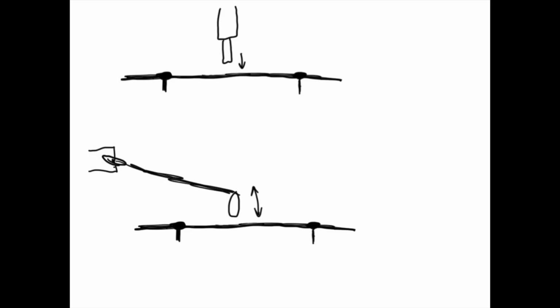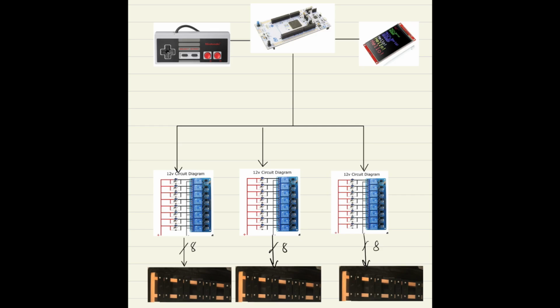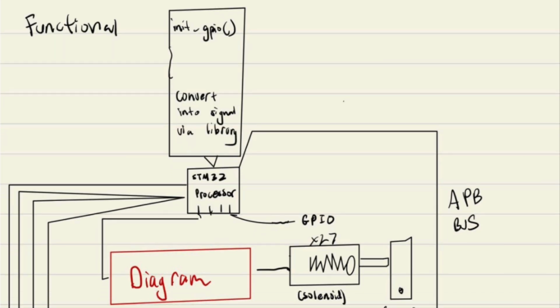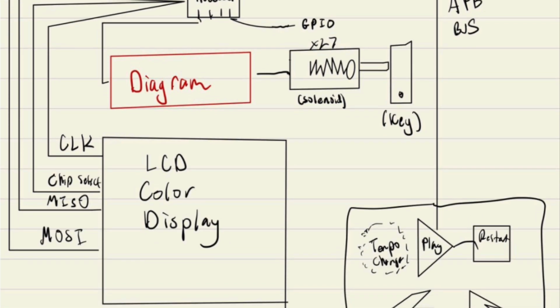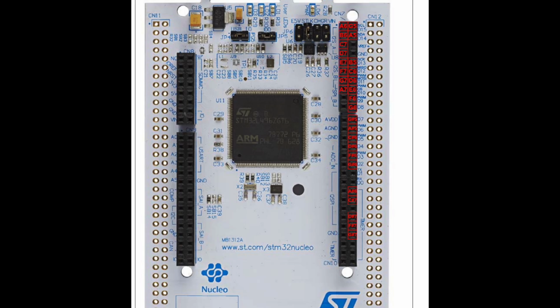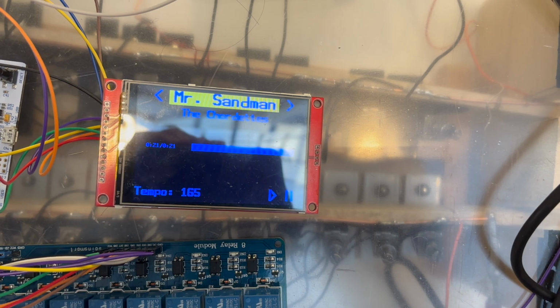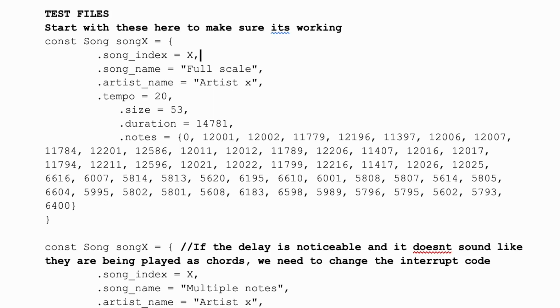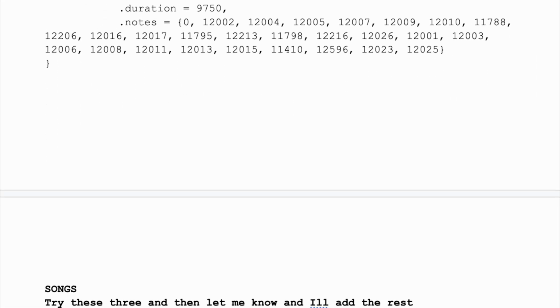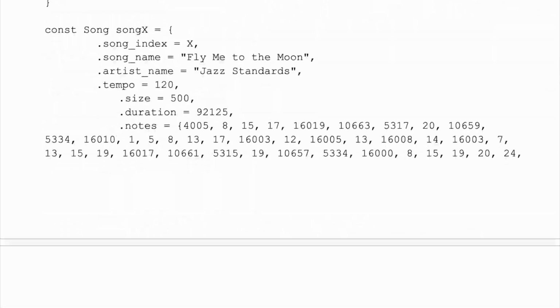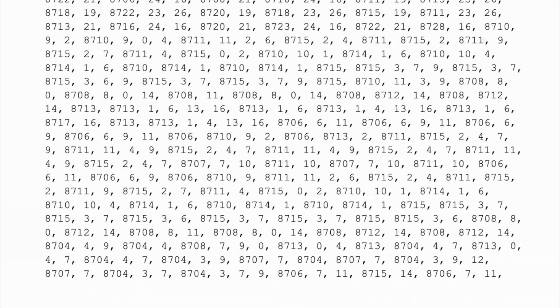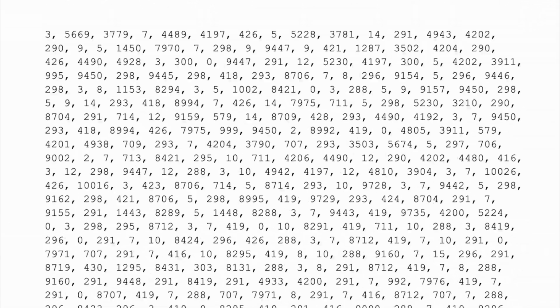After developing our concept, we started making design decisions about how to approach the project. Our approach and implementation involved three different aspects. One part involved leveraging GPIO on the STM32 to trigger the solenoids. Another part involved interfacing the controller and screen with each other in the rest of the program. Lastly, designing a way to store the music data and coordinate it correctly with the timer on the STM32 also presented itself as a considerable technical challenge.